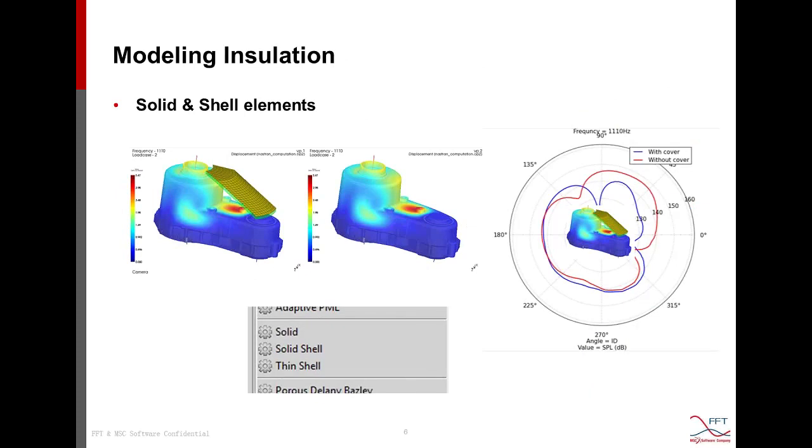Okay, so those were the three methods that I summarized to model absorption, including the internal loss of the fluid by the imaginary part of the speed of sound, the surface absorption by the admittance, and the porous material modeling using the Biot model.